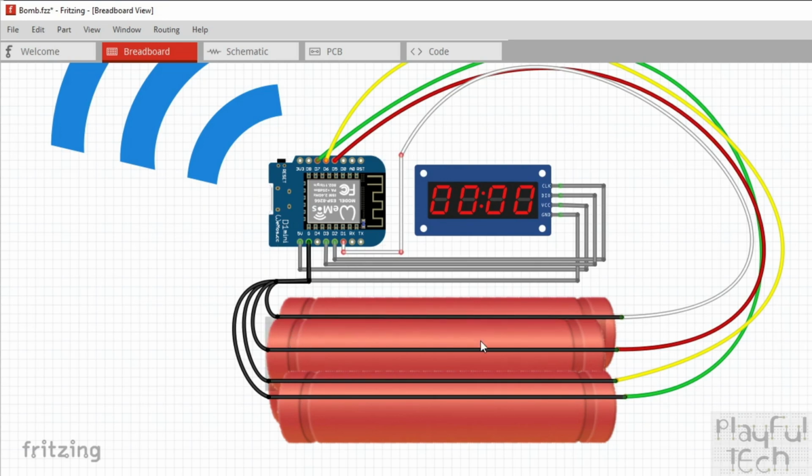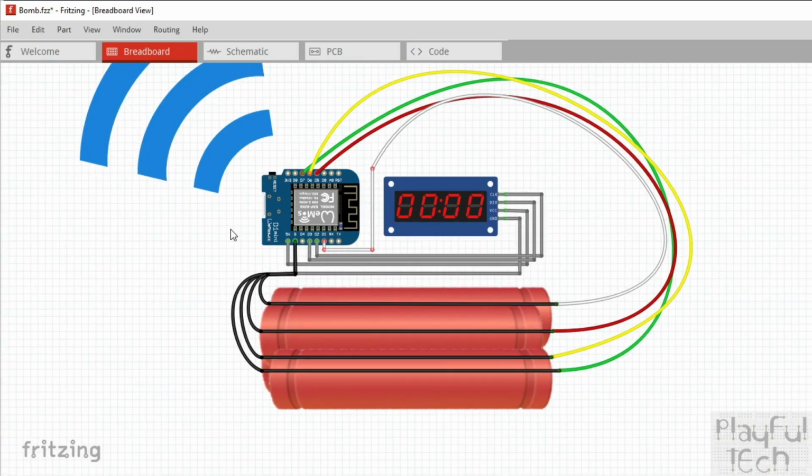And what you could use is, if you have a hollow stick here, as well as using 4 sticks to actually carry the signals, you could effectively have another stick in which you placed 3 C batteries or D batteries, for example, in a row. That would give you 4.5 volts of power, which would be enough to supply the power here. So you could kind of double these up as battery containers as well if you wanted to make the device totally portable. So that's actually all the wiring on that side.